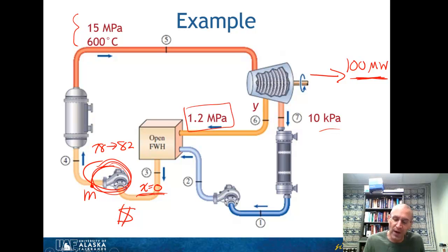So if I go ahead and keep moving this from 0 to 0.1 to 0.2, 0.3, although the thermal efficiency increases, I'm not necessarily making a better plant. I mean, you could just be building this incredibly expensive Taj Mahal power plant that has this incredibly high efficiency, but it's still a 100 megawatt power plant, the same thing that you could have had that wasn't the Taj Mahal. So there are some trade-offs there, so sometimes we don't want to focus too much on thermal efficiency and realize things such as capital costs. Now, costing is a little bit outside the purview of this class, and you'll look at it in other courses, but it's a good thing to recognize why that is.